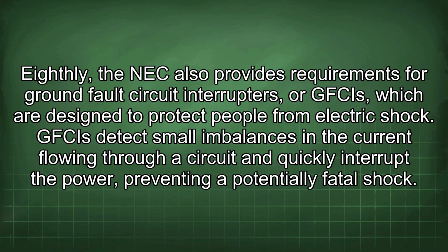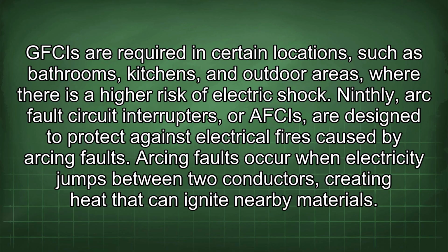Eighthly, the NEC also provides requirements for ground fault circuit interrupters, or GFCIs, which are designed to protect people from electric shock. GFCIs detect small imbalances in the current flowing through circuits and quickly interrupt the power, preventing a potentially fatal shock. GFCIs are required in certain locations such as bathrooms, kitchens, and outdoor areas where there is a higher